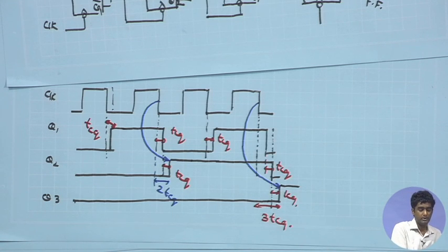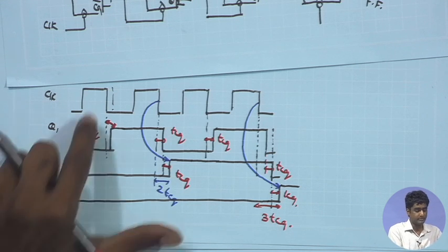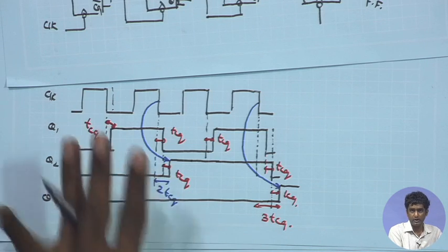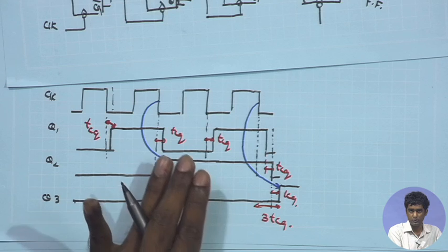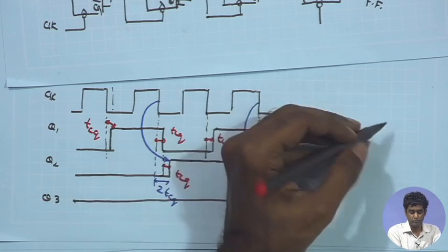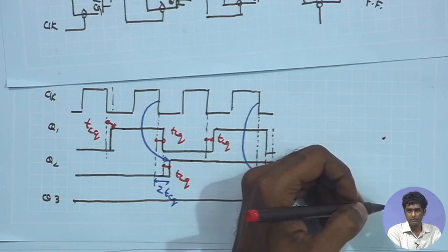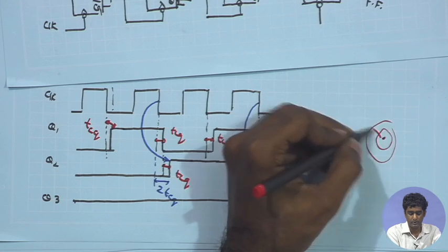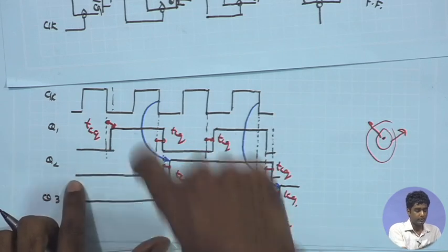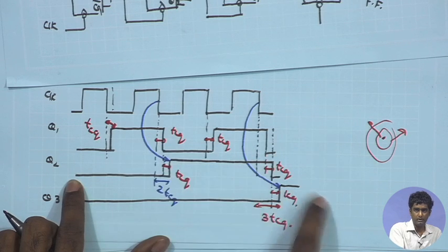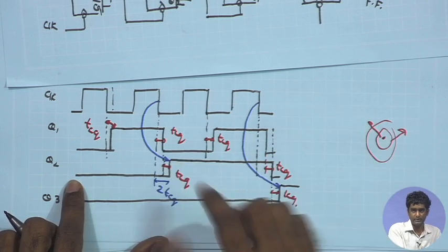for the n stages of the counter, and therefore, what we can say is with respect to the negative transition of the main clock, the outputs are transitioning or rippling from the first output going to the second, third, fourth, and so on. So, there is a ripple going on, just like you drop a stone in a pond, where still water, and you drop a stone, and then you have ripples going on step by step. The same thing, you are having a negative transition over here, and then gradually step by step all are transitioning at the subsequent negative edges after certain delays.